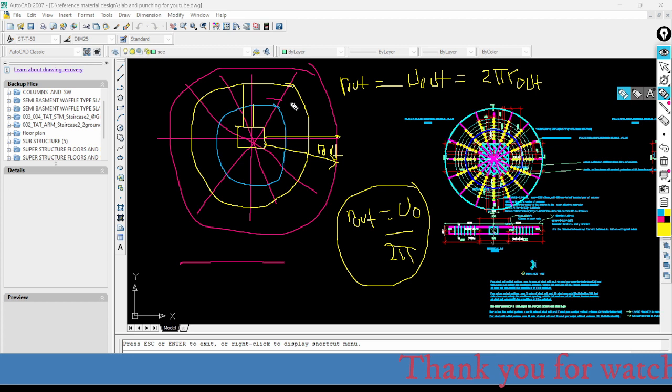And the other point that we need to take into our consideration is the distance between this reinforcement bar and this reinforcement bar, that is located between the basic parameter and the outer parameter, should not be greater than 2d. It must be less than 2d, where d is the effective depth of the slab. So if it is greater than 2d, we need to provide secondary shear reinforcement set here. So we need to provide rebar ties here, just like this.